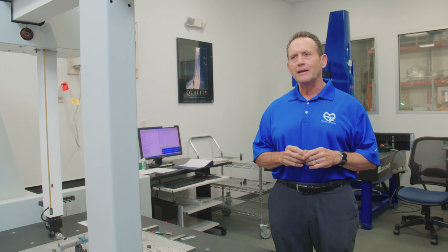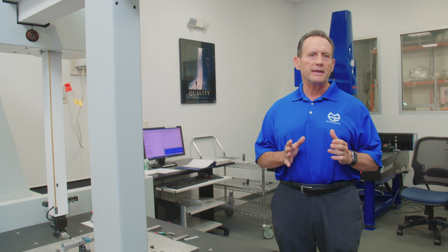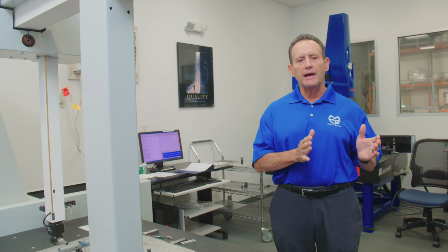Based upon that, also in the control plan will be the frequency of inspection. That's basically set up based upon how well the job is running. That includes the Cp and the Cpk, and if it's running at a certain level, 1.33 or above, there's a certain amount of inspection that takes place. If it's below 1, it's almost 100% inspection at that point.